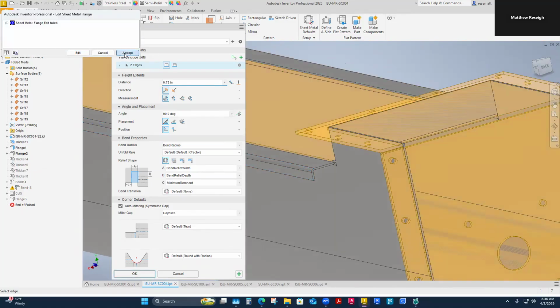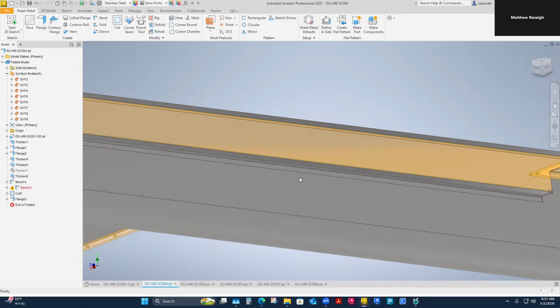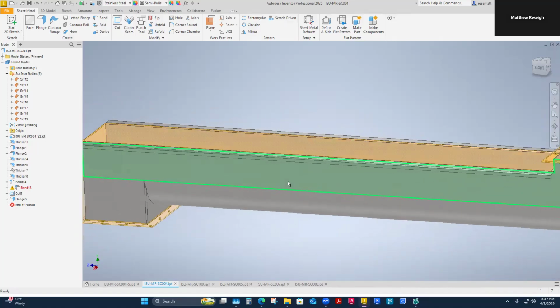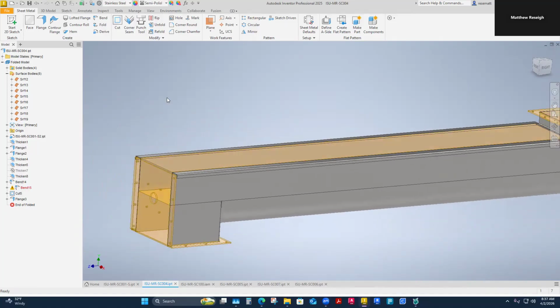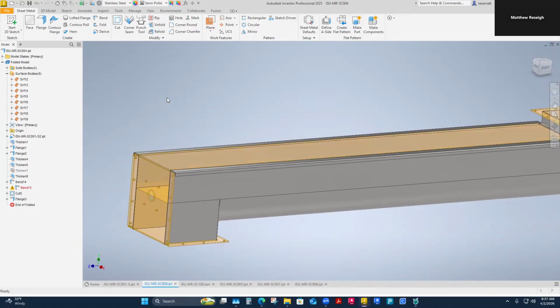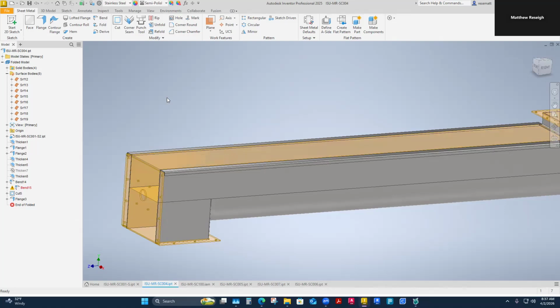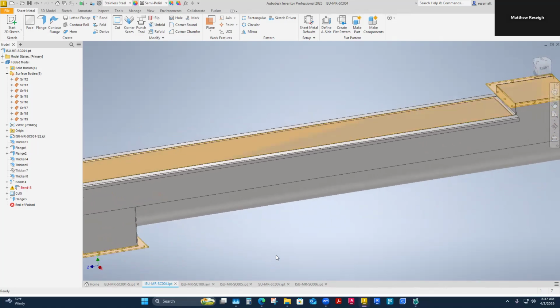If I make a change, or I find an error with how I drove one of my flanges, and I have a bunch of flanges on a part, I may need to go through and follow those changes through, to try to keep them uniform. Because that gets hard to determine too if you've done different things on your flanges. Generally, once you get a flange setting that is predictable by your equipment, there are going to be very few changes you'll make to that. It'll be more of just making sure those are always the same, because they've been vetted by the company to bend on their equipment correctly. It's not like always picking and choosing, like we're doing a little bit ourselves here. But once I find something that works for me, I'll apply that to my other flanges as well. So that corrects that issue.